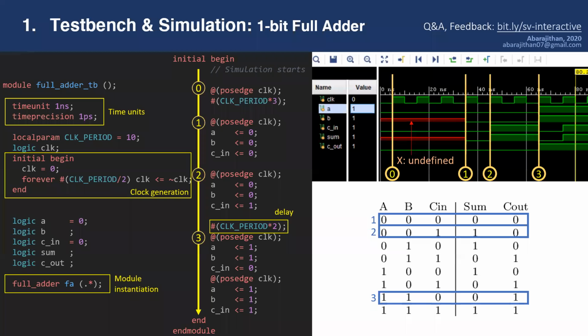Yes, SystemVerilog is okay. I think I answered that question before. Without using always_comb, can we just use assign? You can use assign only if your assignment is one line. If you want to put a multiplexer, it is very difficult to do with assign. You can still do it, but it's quite difficult. Other than that, we will use always_comb. You will see it in the next examples.